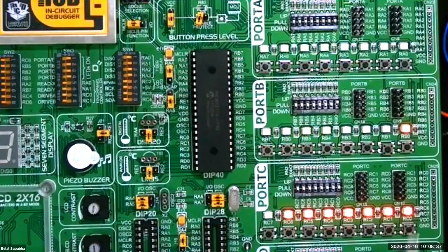This is port C. All LEDs 0, 1, 2, 3, up to 7 are blinking, but RC7, which is the 8th LED, is off because it is connected to the motor, so the motor is off. The higher 4 bits of port B are also blinking. The lower 4 bits are inputs. This is the push button. When we pushed the push button, the blinking should freeze, and port C should turn on. It didn't work. When I pressed the button last time, this is what we had.